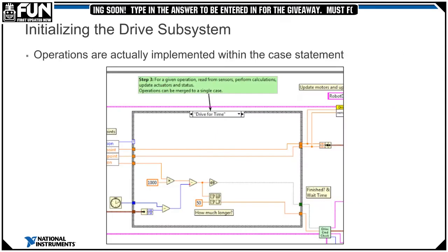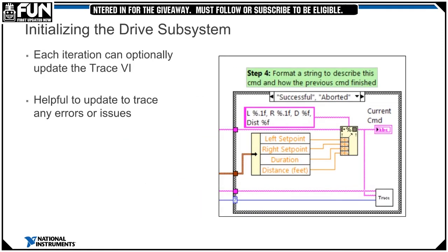Because we definitely don't want to get close to that safety timeout, because if we miss it due to execution time or your vision processing loop is slowing everything down, it'll actually time out all your motors. So we definitely want to make sure we're updating it frequently enough to catch that safety timeout, basically. We're just playing it safe here. Cool.